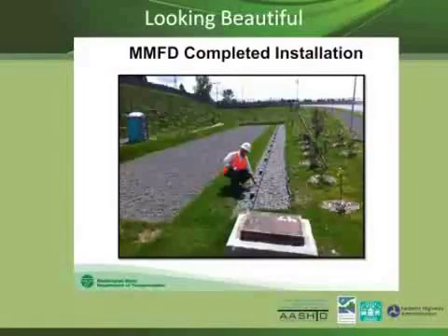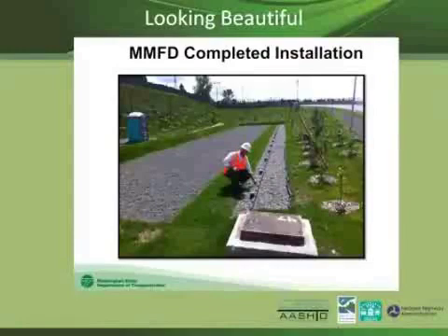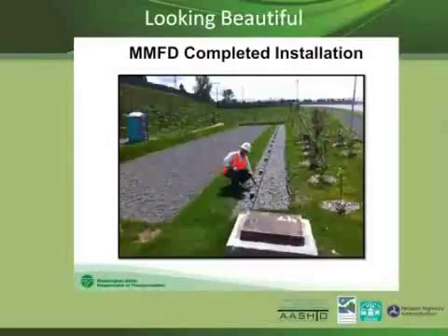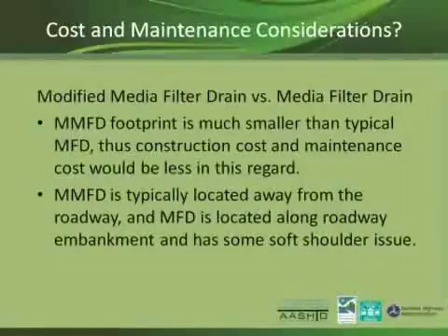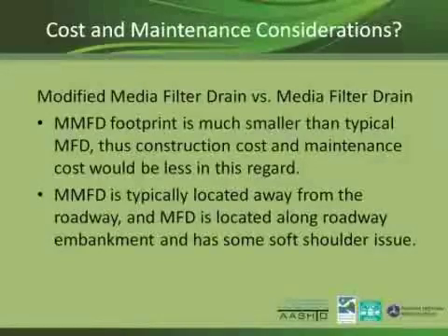This is the final product. If you look at the picture where the man was sitting down right there, on the right-hand side, which you cannot really see, is an 18-inch probe pipe, and then you can see a V-notch weir there. The water will go over the top of that weir, and go over another couple feet or 1 foot of the rubble section, and then go over a 4-foot section of the rack, and then go to a treatment media filter drain there. On the left-hand side, there will be a 12-inch probe pipe underneath that you cannot really see. So again, what we're seeing here is a treatment BMP that is not available in our stormwater menu, nor probably in any stormwater menu in the nation.